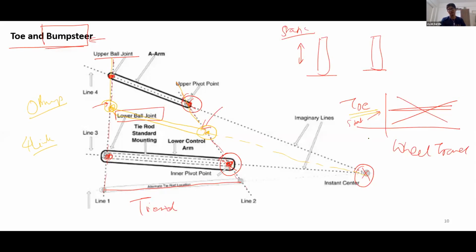that your car should maintain. So let's again talk about optimum angles over here. For acceleration and braking, your toe should be 0 degrees, absolutely vertical. And for cornering, don't rely on toe to optimize cornering. Instead, use steer angles to improve cornering. Steer angle is the angle that your steering system produces due to rack motion, how much of steer angle is produced. So this is the optimum angle for toe.